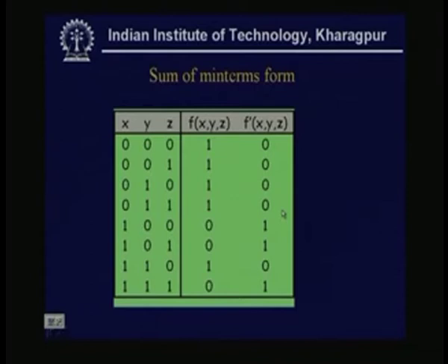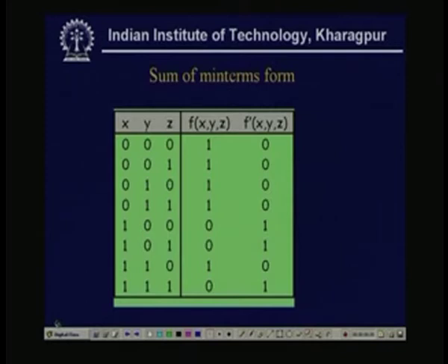See, this is one example. So, these are the minterms, all possible values I have taken. This is the truth table x, y, z, and these are the outputs. See, there are two outputs, the function f and f complement also. So, when m0, that means x, y, z all are 0, then it becomes 1.